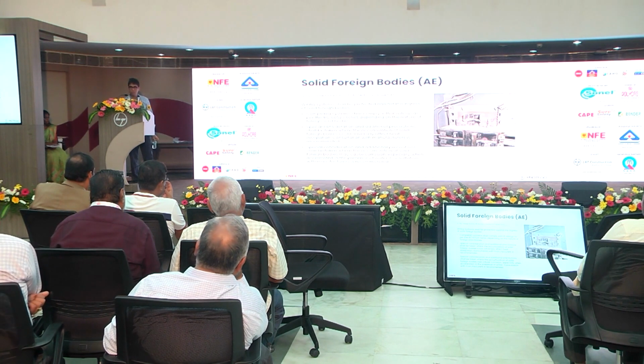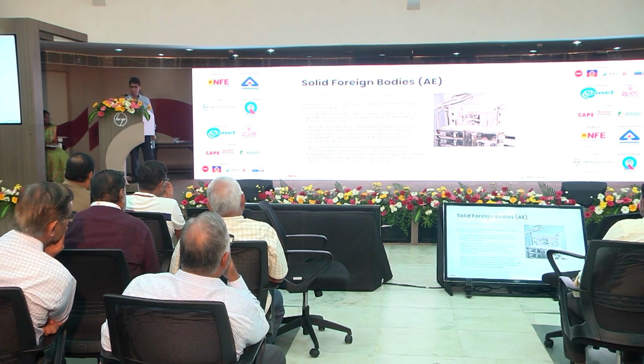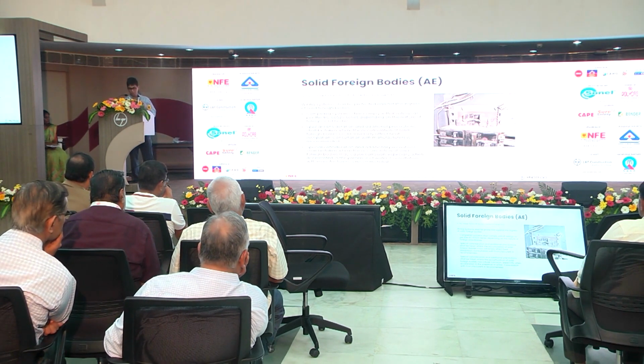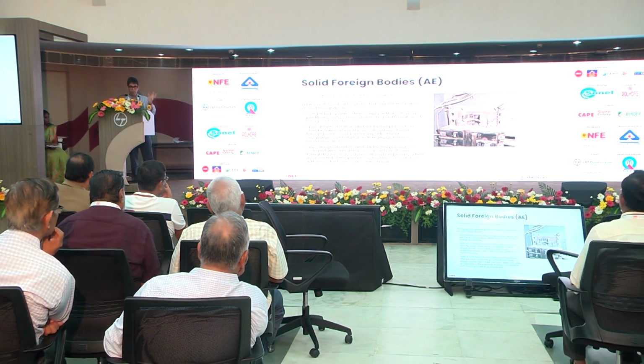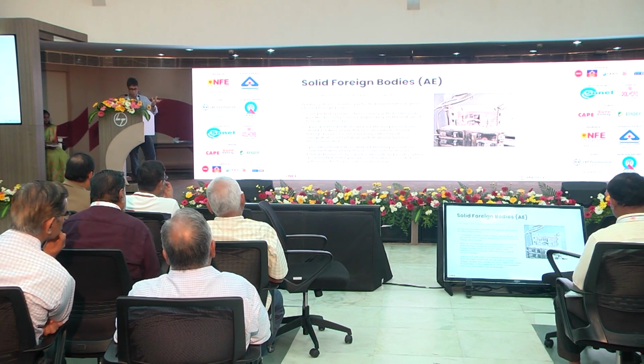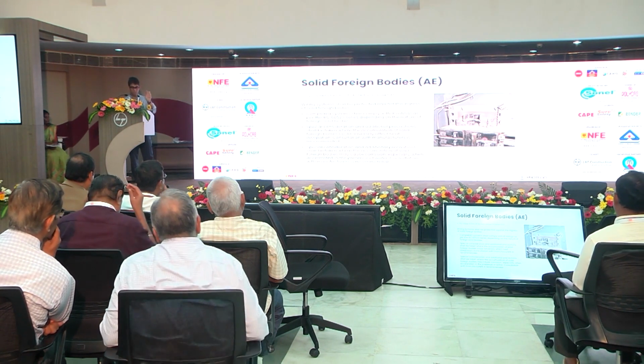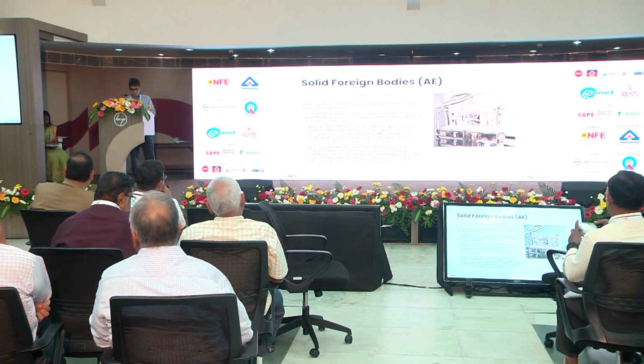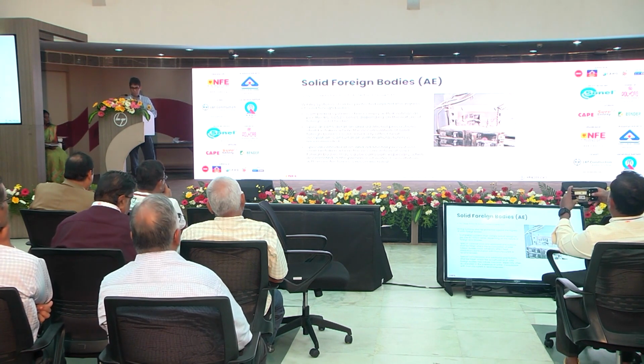And these circuit breakers usually are only rated for use with a certain level of pollution in the atmosphere or a certain level of foreign bodies. If you look at their manufacturing catalogs, you'll see this information there. So again, the IP rating comes into place here.